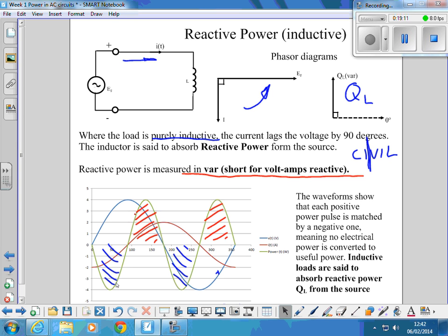Say, for example, you're using that coil to do some mechanical work. Is that going to cause a phase shift? Say, for example, in a solenoid, would that cause a momentary phase shift? If that coil is what we're modelling here, an absolutely pure inductor, i.e. Henrys only and no ohms, which is not achievable in real life, you would get a 90 degree phase shift between voltage and current, as shown on this diagram here.